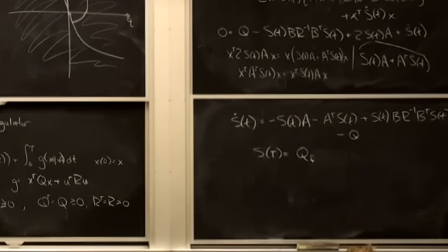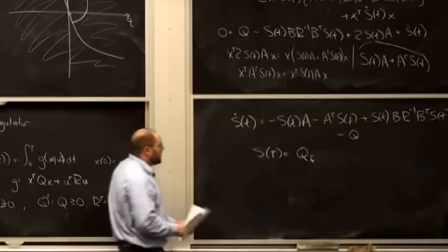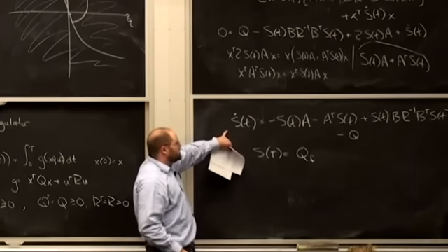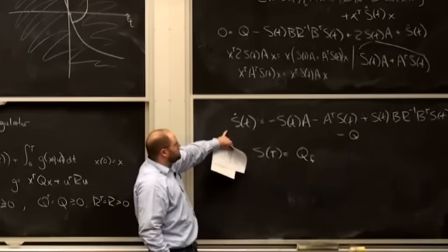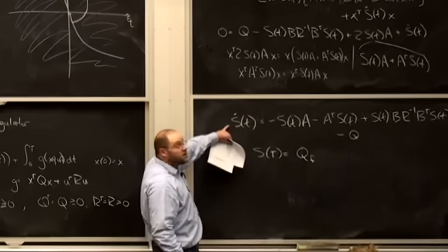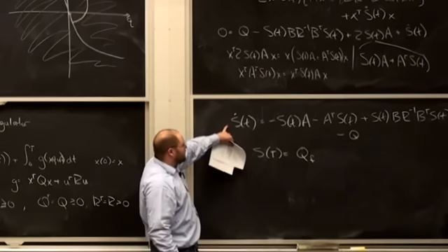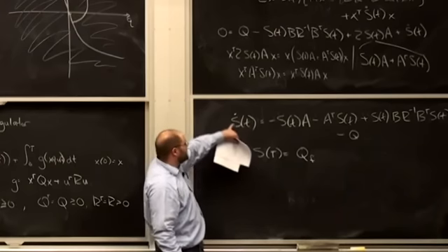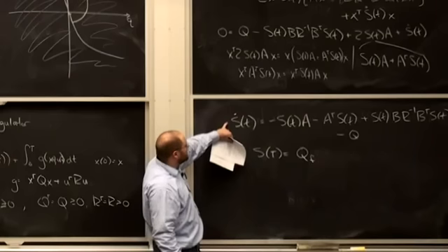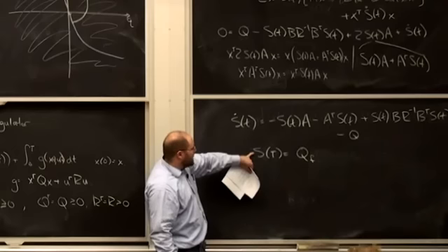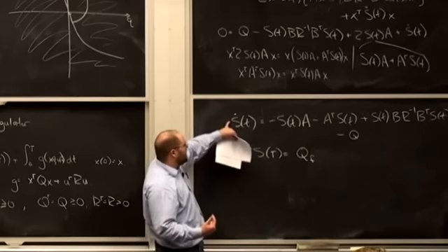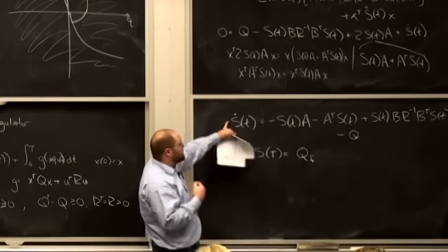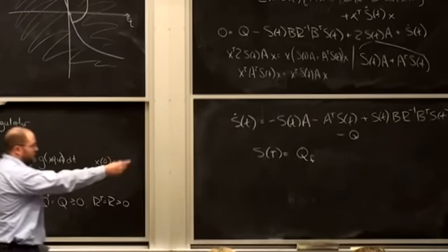So, a direct application of the Hamilton-Jacobi-Bellman equation, I was able to derive this Riccati equation, which gives me a solution for the value function. It gives me a final condition on S, and then the governing equation, which integrates the equation backwards from capital T to 0.